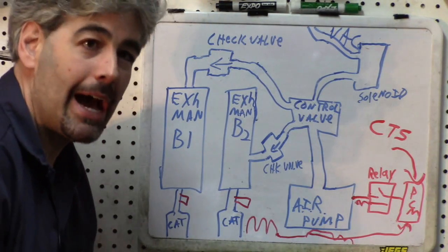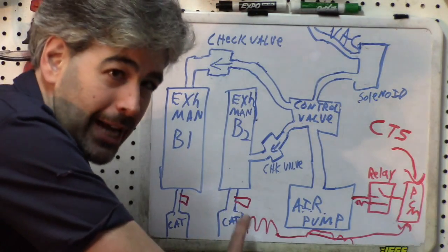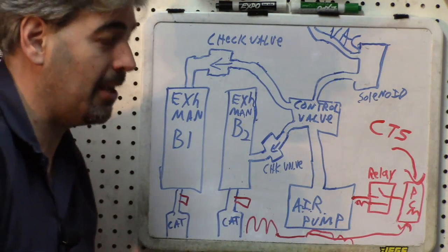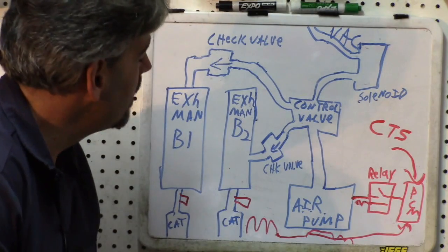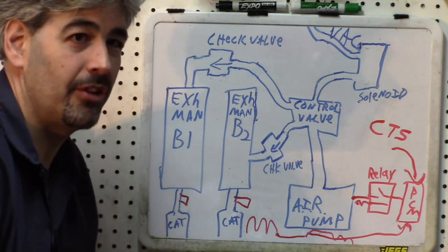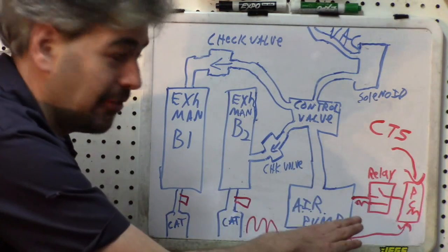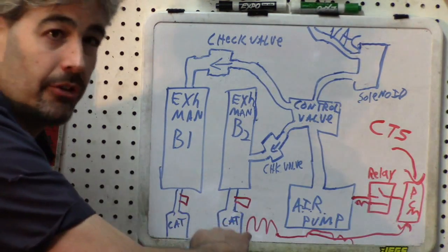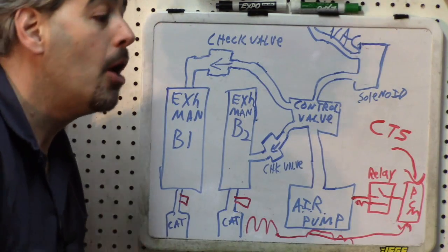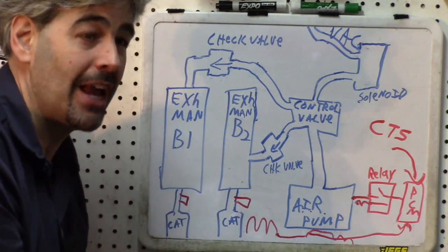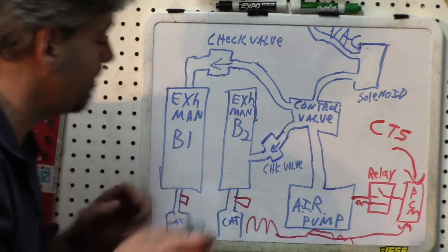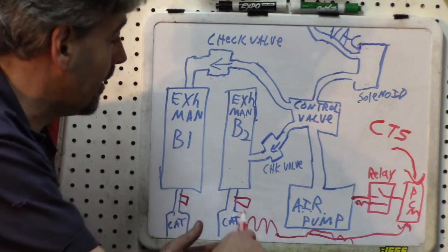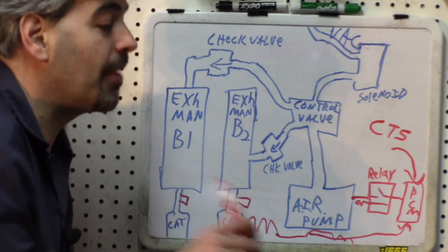So think about it. How does this work then? Because this is actually how the PCM knows. How does this work if the air system is supposed to be operational in open loop? So the answer is ridiculously simple. Nobody said that this test has to occur during open loop. What actually happens is this test of the air system will occur at some time when the engine is known to be in closed loop by the PCM so that it can see these responses. Now, hopefully you're noticing a pattern with this Diagnosis and Understanding series, that you can never really master one system without knowing other systems.